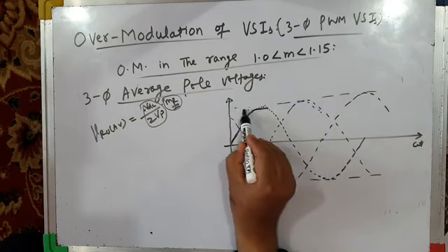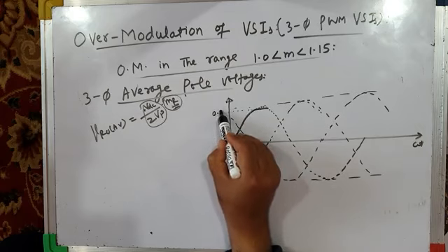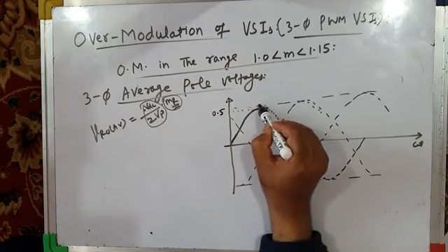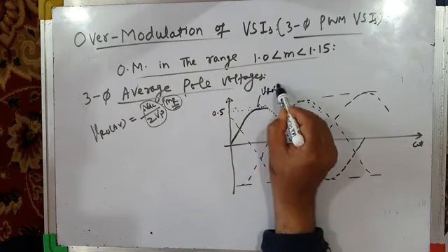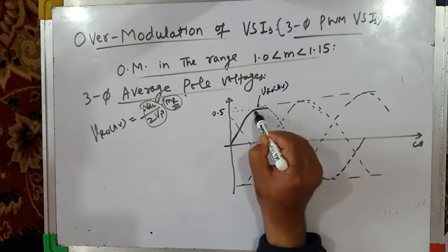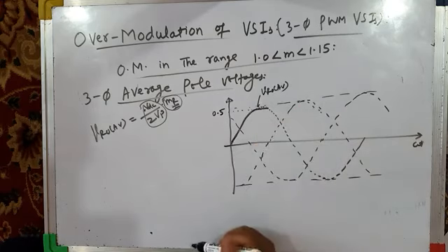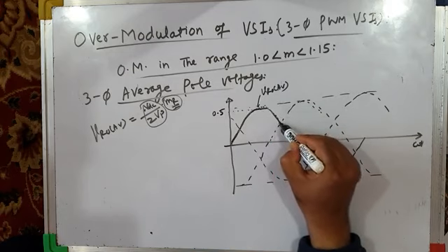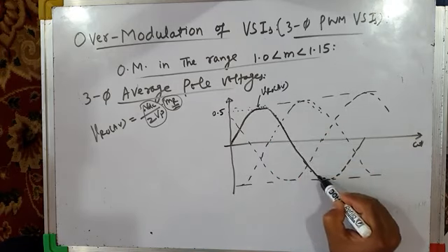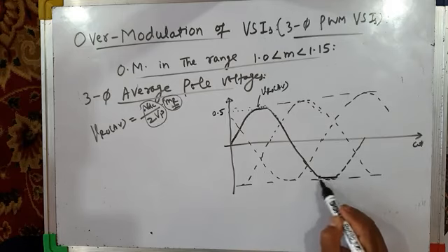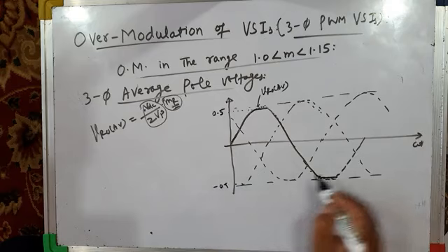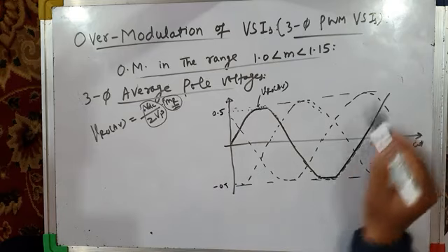The inverter instantaneous average pole voltage is 0.5. Okay. Because what is the pole voltage VRO during this period? This is VRO average. The pole voltage during the bus clamping period, when there is pulse dropping, is plus VDC by 2. So it is 0.5. Its amplitude is 0.5. Then it again follows MR, and then there is again pulse dropping here. It is minus 0.5, minus 0.5. Then it goes like this.